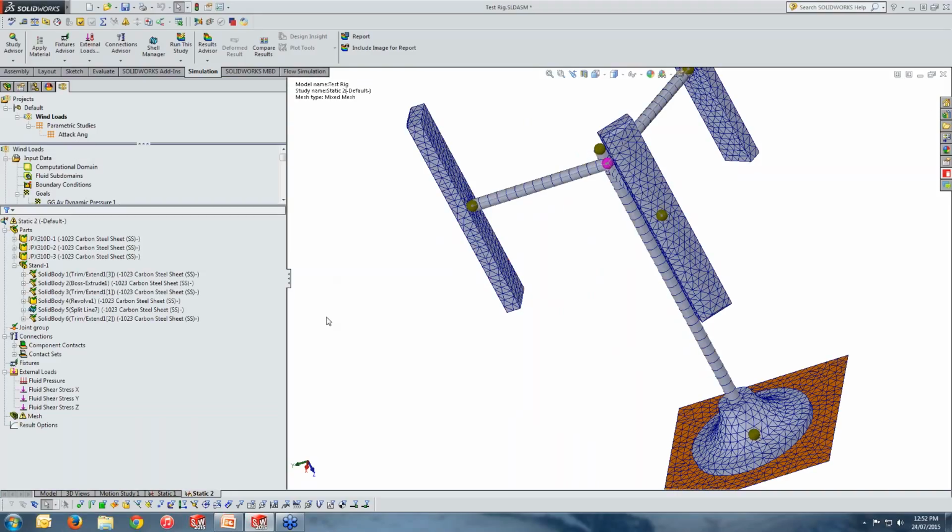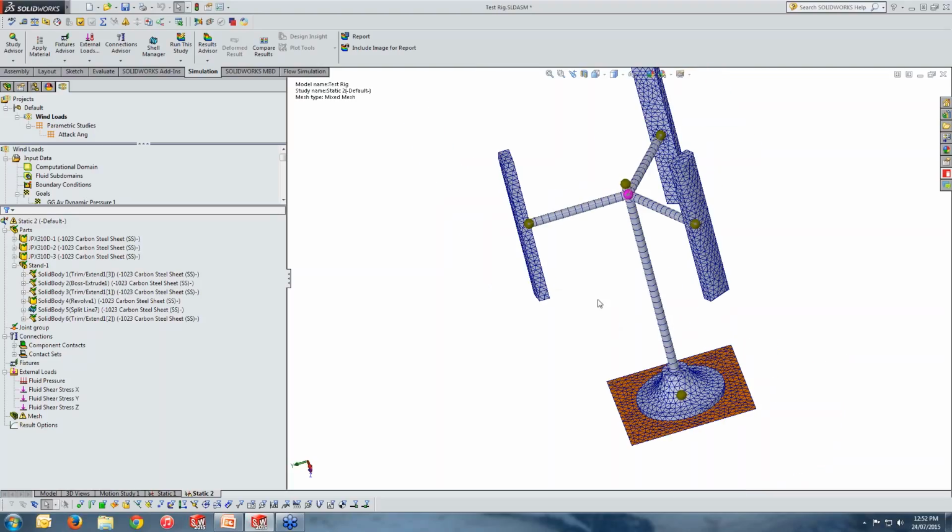That is something very important. If you don't, then the bonded contact between these two types of elements either does not get established, or you might create a hinge connection, and this can simply rotate against the beam element. That is something that needs to be done in order to complete the process.